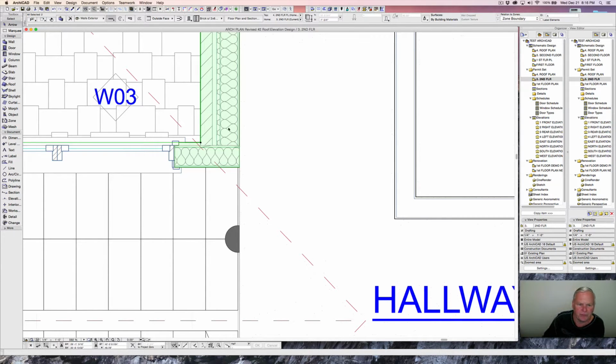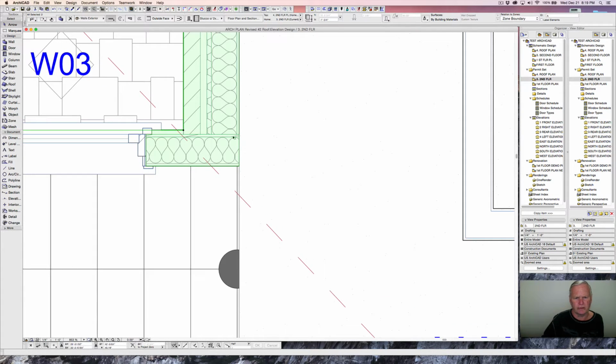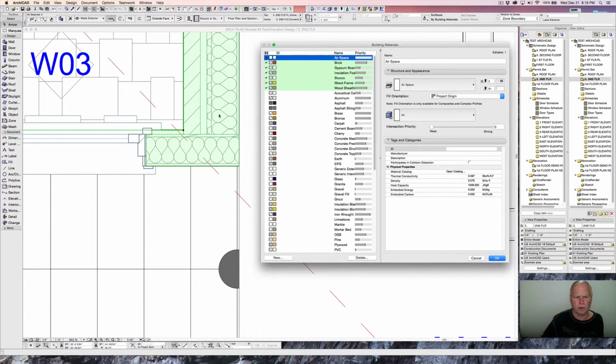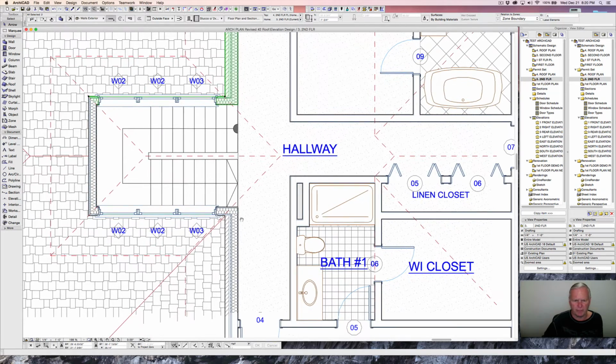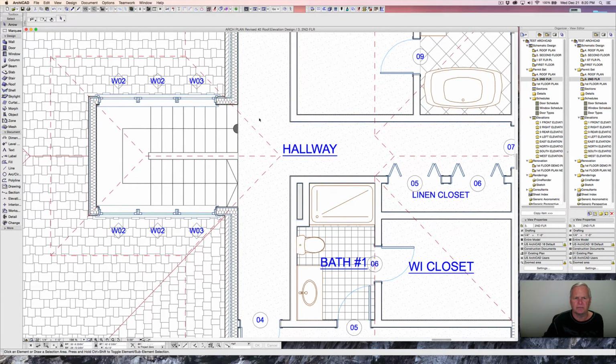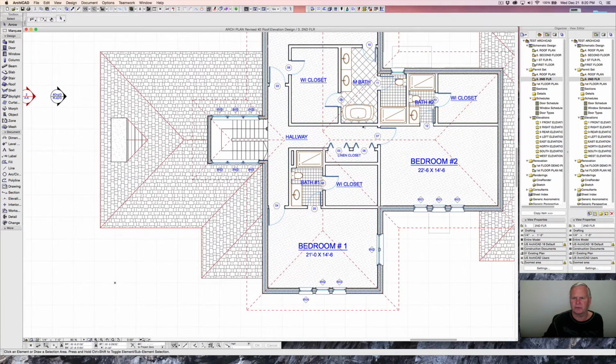Now, as far as this wall and this wall connecting as it should, what we want to do here is we need to look at those settings, and this wall here needs to be set a little stronger than that sheathing there. That sheathing now being 710, so the wood frame there, which is this, needs to be set for, let's say, 715, and say OK, and now that's shown correctly. So we've got both sides have changed accordingly, and that now looks the way it's supposed to look.